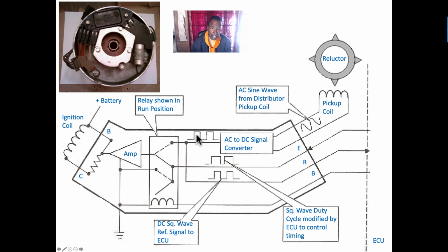So that's positive here. Remember that? I need a positive signal to the base of the transistor. That's going this way to the transistor. But back over here, I get an RPM signal in the computer, so the computer knows the car is cranking. Once I see that, the computer's gonna send a 5-volt bypass out. When you go check the timing for spark or engine performance, you're gonna say disconnect the black wire with brown tracer on the 4-wire connector, because you're disconnecting this bypass wire. This 5 volts is gonna be delivered to this wire, to this coil, to ground, like a relay. I'm gonna switch from cranking mode to running mode.